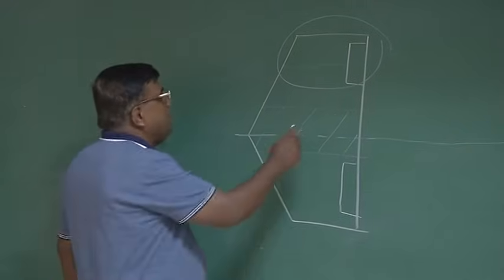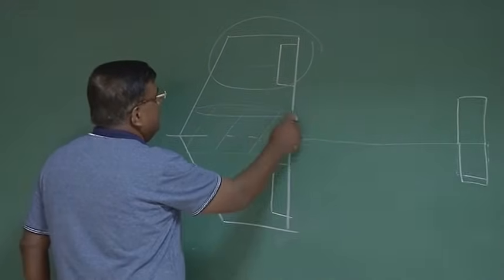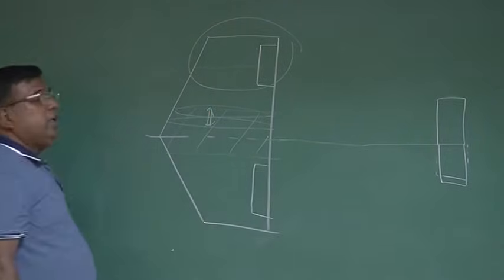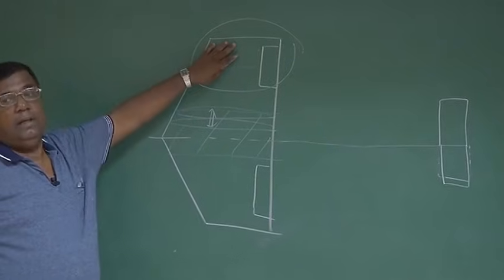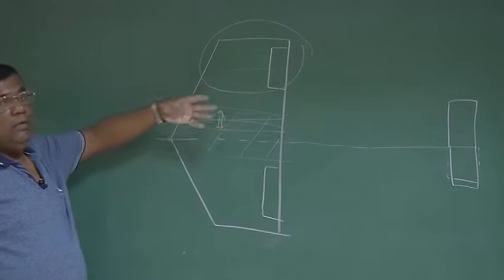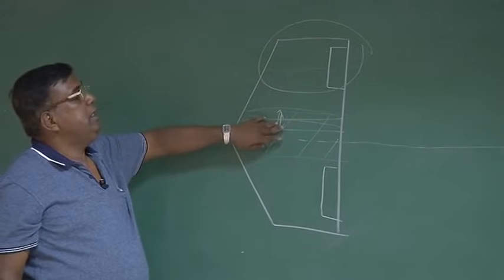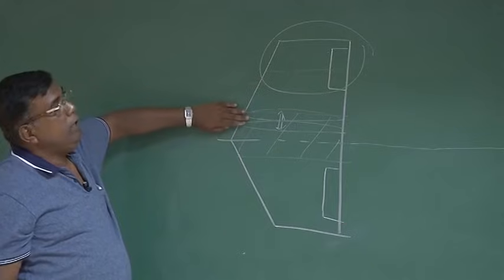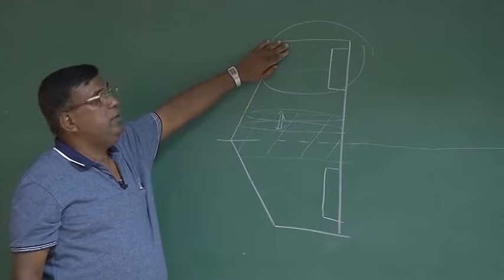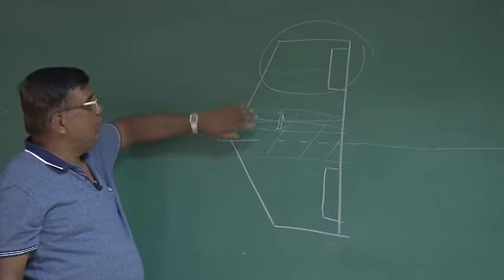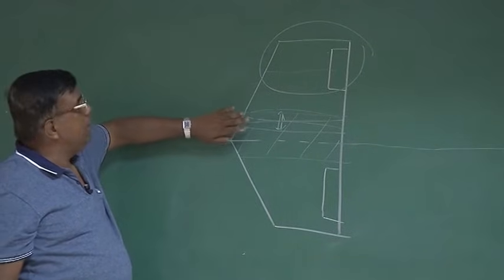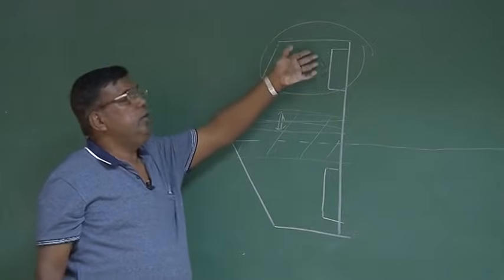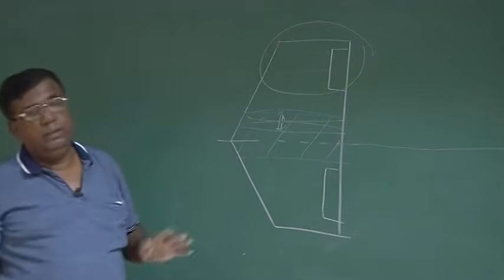Another way is you select an aerofoil such that the aerofoil here has a smaller stall angle compared to the aerofoil there. That is, one of the ways it could be handled is by adjusting the t/c of the aerofoil here. Let's say this aerofoil will stall at 12 degrees, and this aerofoil will stall at around, let's say, 13 degrees. So even if there is a stall situation, this portion will stall, and this will give a warning to the pilot, and he can control the airplane through aileron. So this is also possible.